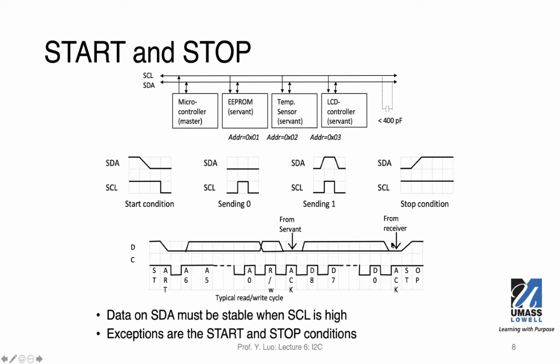This is another reason why we use logic high on both wires to indicate an idle status, simply because we use 0 to indicate the acknowledgement. Then after that, we stop the pulse, and we return the SDA line to high, so we end up having a stop condition, and this whole transaction finishes.